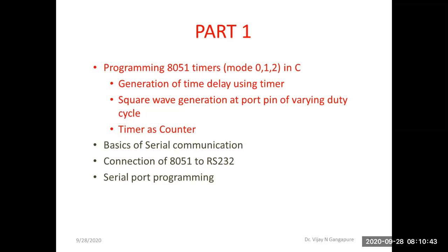To use these timers, there are SFRs associated with timer 0 and timer 1. These SFRs are Tmod SFR, that is to configure these timers, timer 0 and timer 1. Then Tcon SFR, timer control SFR, to control the operation of these timers.